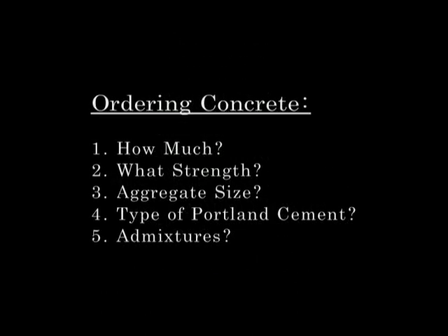You want to order your concrete about 2 days in advance. That way you can be sure that a truck will be available when you're ready to do your pour. When you call the yard, they'll want to know how much concrete you want to order, what strength, the aggregate size, type of Portland cement, and what, if any, admixtures you want placed into the mix. Some of this information is basically standardized, whether you're doing flat work or doing structural foundation walls. Now we'll lay out some of the details of how to address which admixtures, if any, you want to put in, which aggregate size to pick, and strengths.